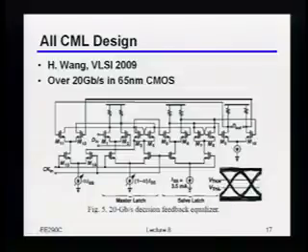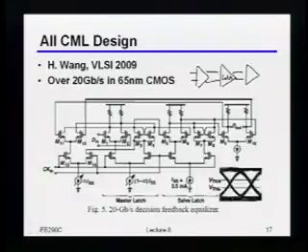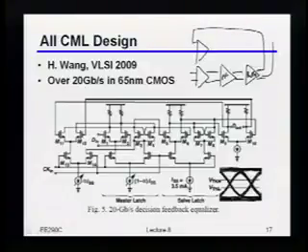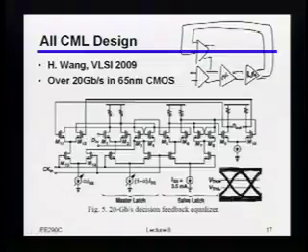So this thing looks a little bit funny, but it turns out it's actually not that complicated. All it's really doing is something like the following. You basically have this input summer amplifier that then goes into the first CML latch or flip-flop. Actually, I'll call this a flip-flop because that's really what it is. It then comes out through a buffer, and that buffer just feeds back to what you can think of as the current steering switches to subtract off of that analog summing node right there.